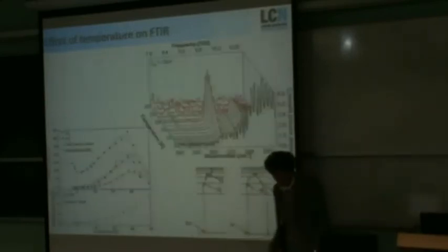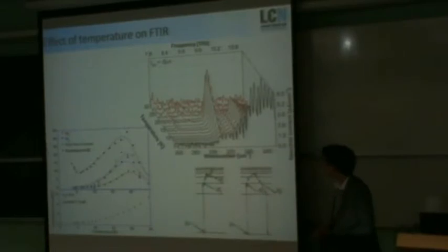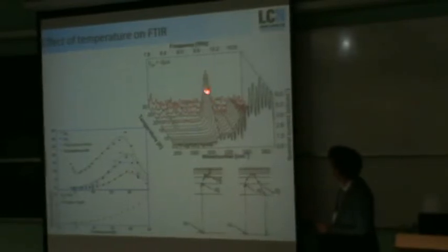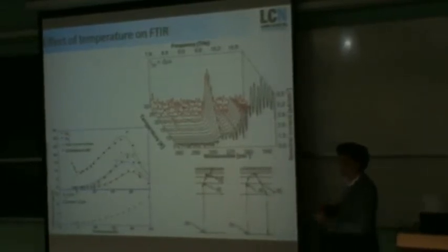Okay, so moving on from that, we've been able to explore a few of the other parameters of this device. I've already alluded to the idea that temperature is an important factor in these types of measurements. So here what we've done is just looked at the temperature effect. And as you can see, in terms of this 2p state, you're getting a peak arising in temperature. The reason this happens is that at low temperature, you're not really exciting many electrons all the way to the conduction band. They're preferentially becoming de-excited back to the ground state.